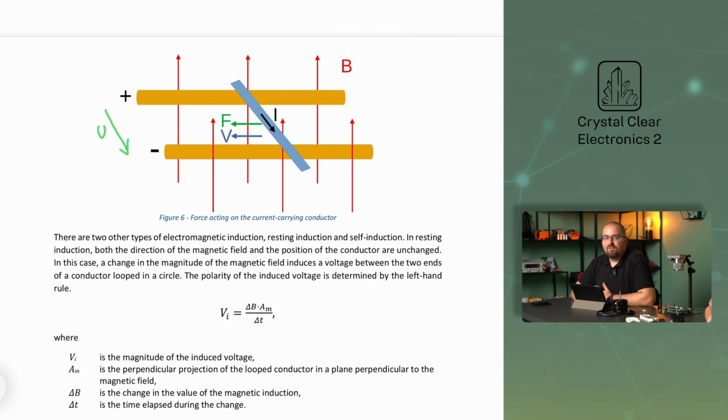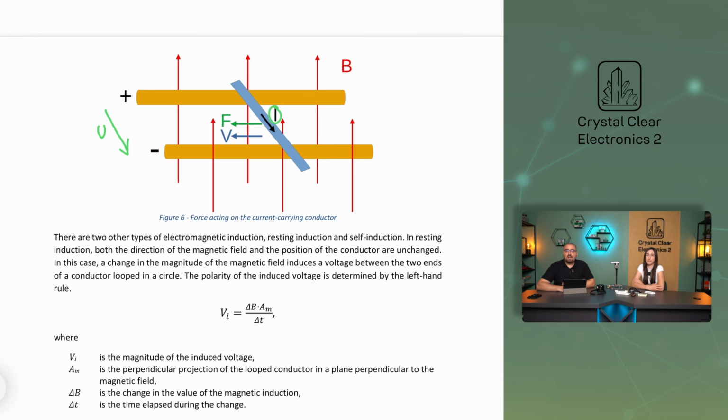The voltage will cause a current to flow through the rod, which is nothing more than a flow of electrons, and the moving charges will interact with the magnetic field. We can determine the direction of the resulting Lorentz force by the right-hand rule. Now, the direction of the charge's motion is the same as the direction of the current, and the magnetic induction vector is pointing upwards, so the force will move the rod towards the left side of the figure, which results in the rod's velocity vector being in that direction.